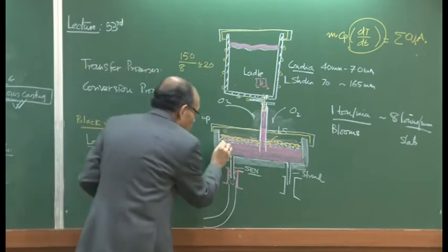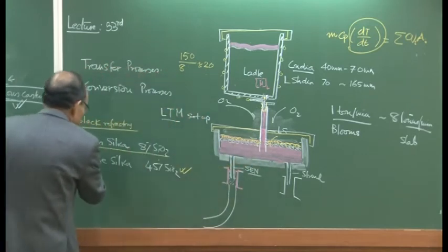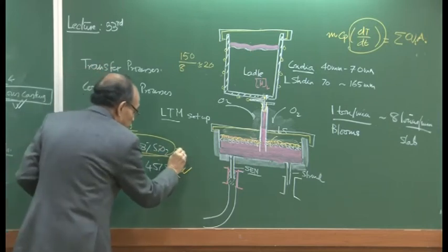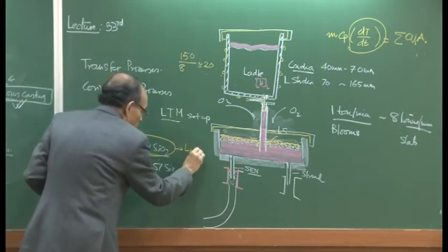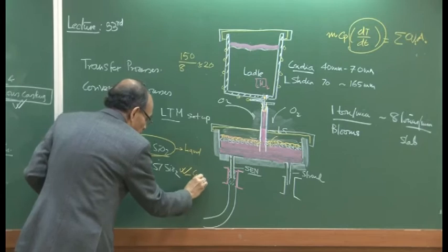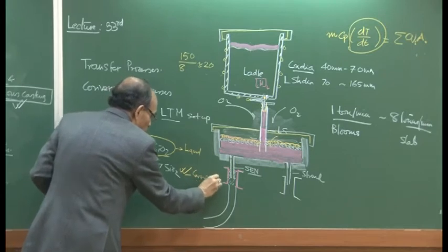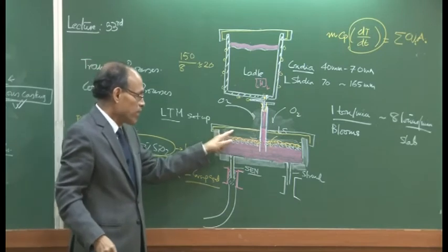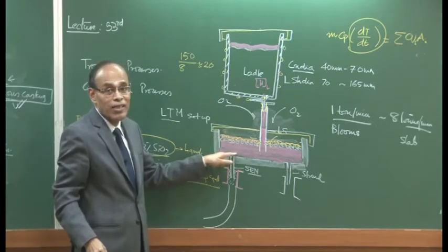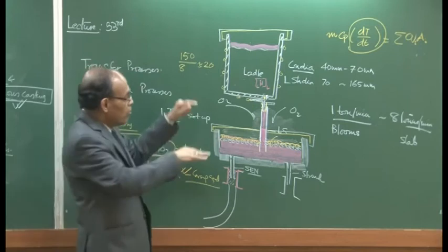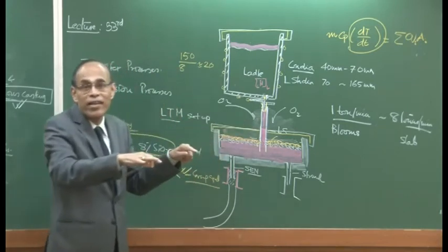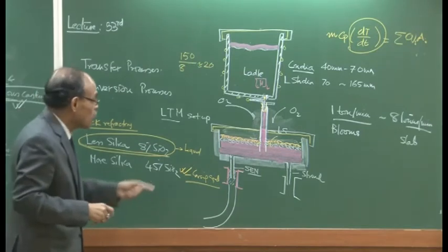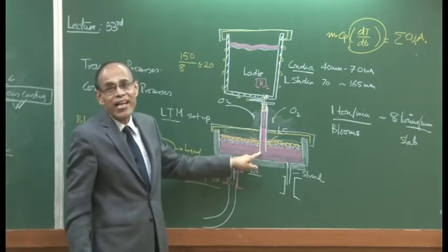So this is the liquid slag, and it is going to be the covering agent. That is going to prevent any further atmospheric contact with the molten metal till the flow rates are adjusted, and that is why I say that we want the shroud tip to be submerged as early as possible.